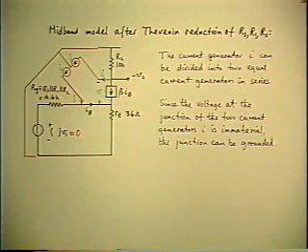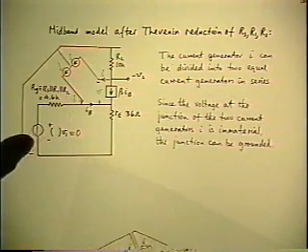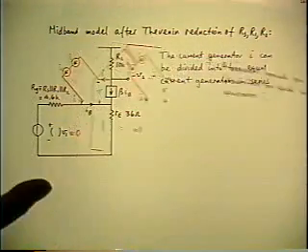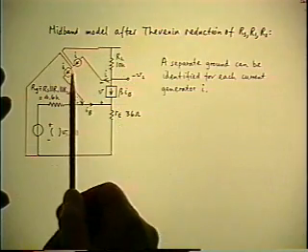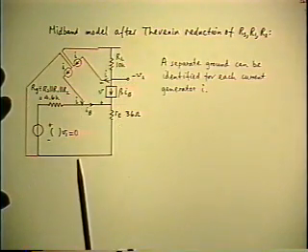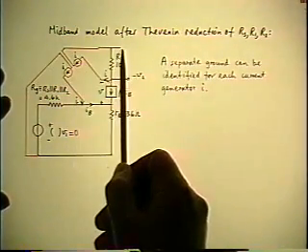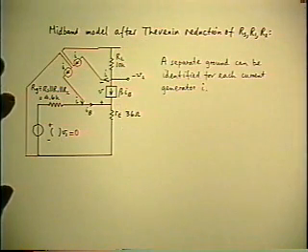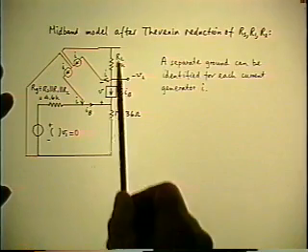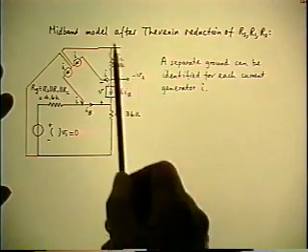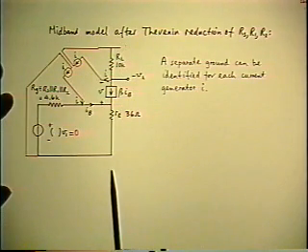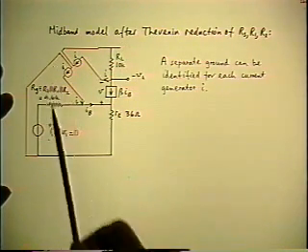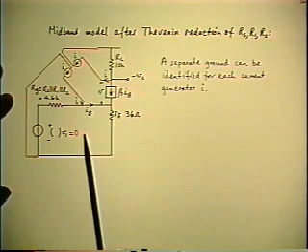But I can make a little change now. I can separate that connection into two different connections, one connected to the AC ground at the bottom, the other connected to AC ground at the top, and still nothing is any different. Because remember, there's an implied AC ground connection from the supply to the bottom anyway. So the circuit still doesn't know anything different happened.